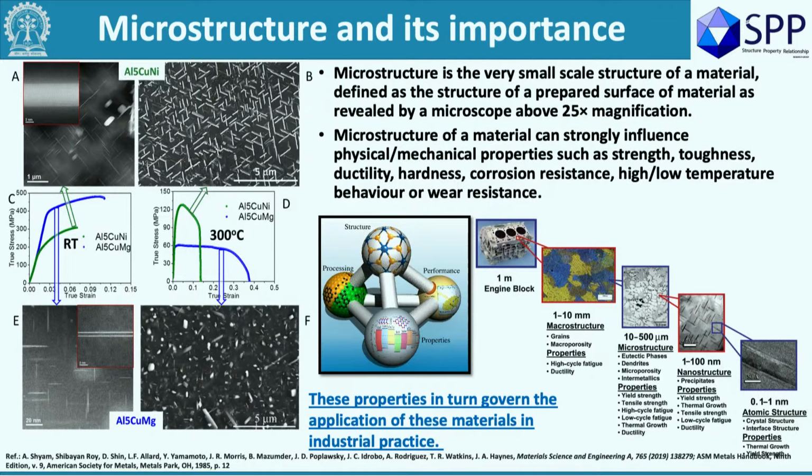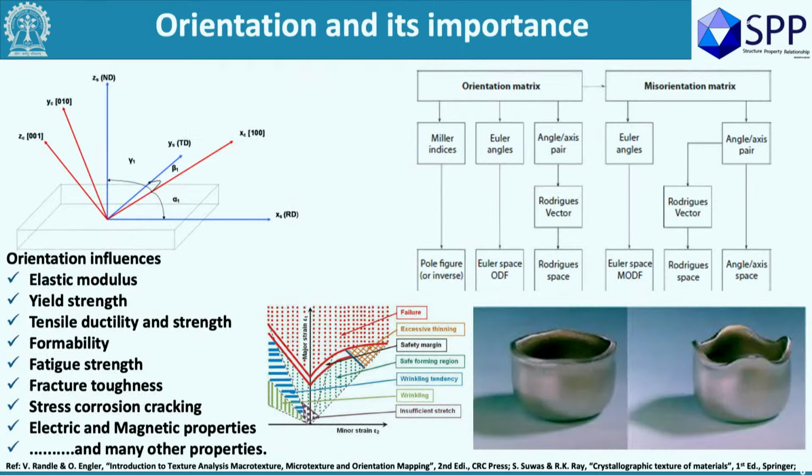So for example, I have shown you one work from aluminum alloys, not titanium, where you have some nanoscale precipitates. When they are fine sized and nicely coherent, you can get a very high strength, and when they are coarse and incoherent, theta prime, you lose all of this. So it is very easy to appreciate that. Something is happening in front of you. You do microscopy, you get to see it. Compared to that, texture was a little more difficult to appreciate, particularly because of that mathematical problem.